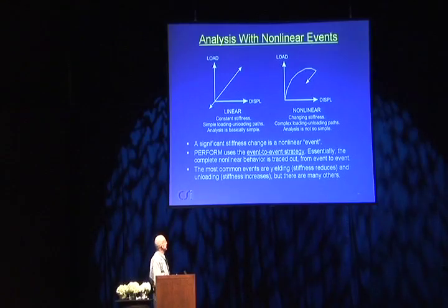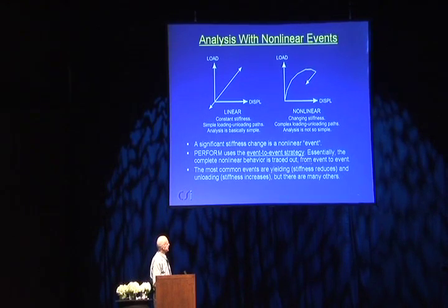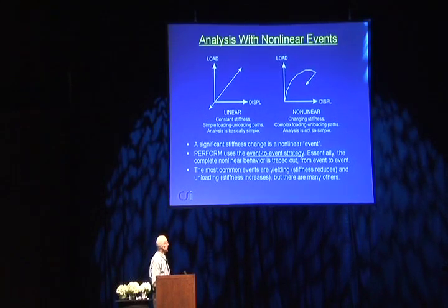The key point is that a significant stiffness change is a nonlinear event. And in this particular case, we have yielding events and an unloading event. So the most common events are yielding, where the stiffness reduces, and unloading, where the stiffness increases.